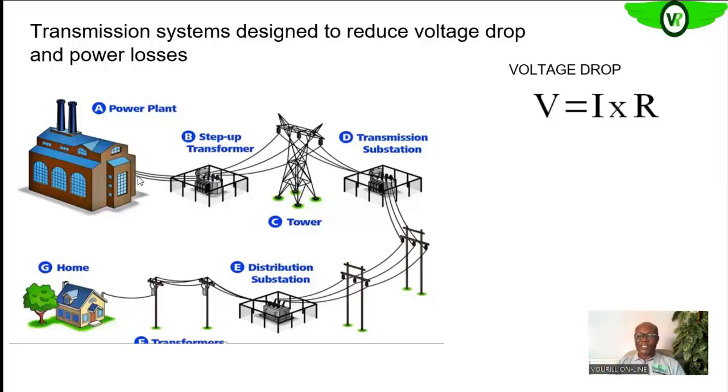It therefore means that if 11 kV is generated here, we will not have that exact amount of 11 kV here, because there are some drops along the line. That would mean that the more load we have on the network, the more drop we'll have on the system. And that is not a desirable condition, okay? We want to minimize the drop as much as possible. We want to have the required amount of voltage at the end where we actually require it.